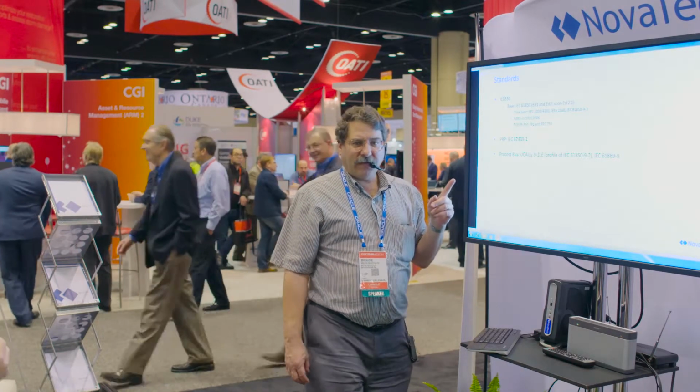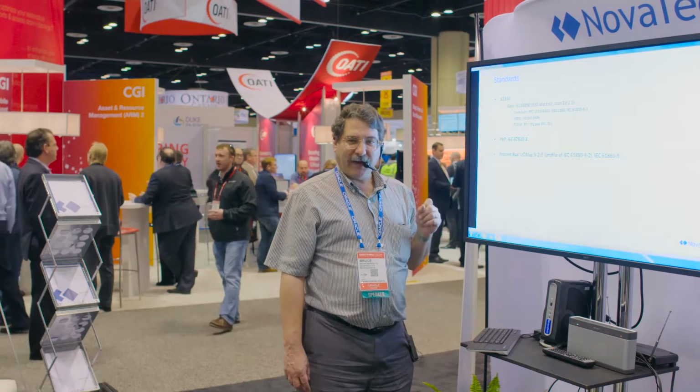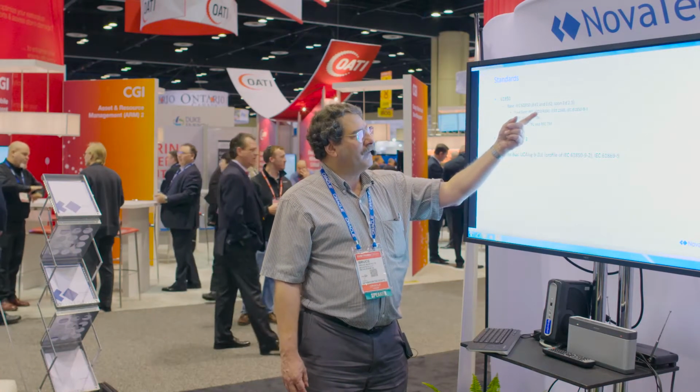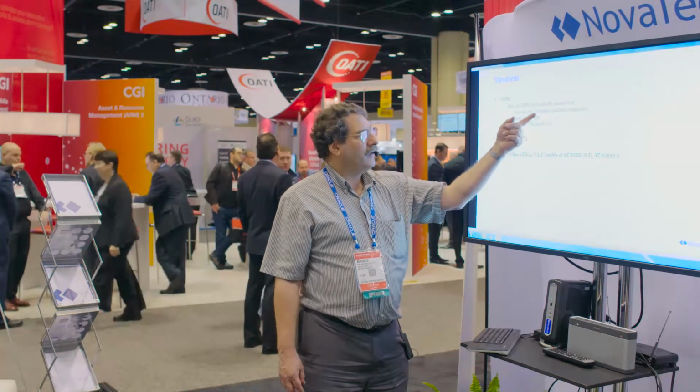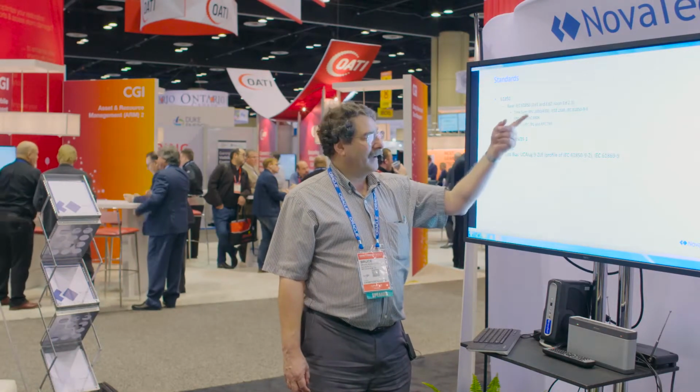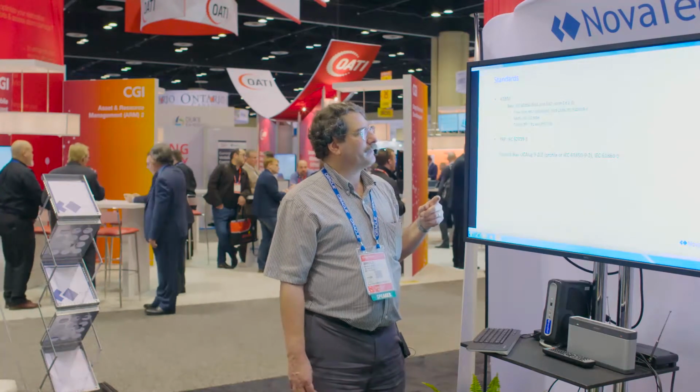The standards that are used in 61850. Remember, 61850 is a collection of standards. They didn't really invent very much on their own. So they used a bunch of existing ones. For example, for time synchronization, they used RFC 2030 and RFC 4330, which is Simple Network Time Protocol. That's been in use since 1983. Very well thought out and very well standardized. They do have security in here for time distribution.